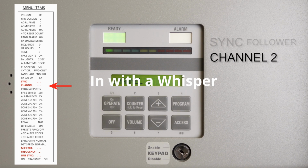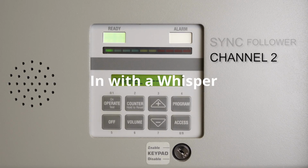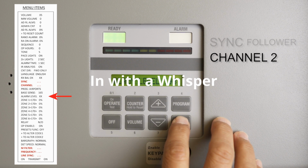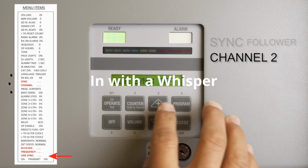If you recall, our leader unit is set to Channel 1. Subsequent units in the approximate location to the leader should always be Channel 2. If the channel menu item shows dashes, change the line sync to on.